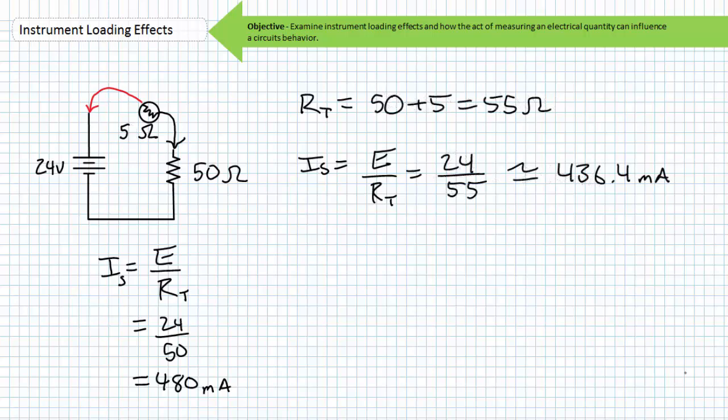Before we move on to discuss the less than ideal nature of voltmeters, let's talk about voltage distribution in circuits using less than ideal ammeters. Realize the internal resistance presented by an ammeter is a series resistance across which a voltage drop will occur.